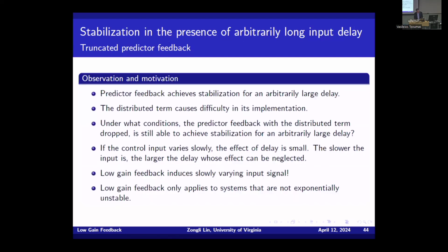So the motivation we had here is delay feedback. This is not good, right? Now, the idea here, you look at this point in two ways. One is, as I mentioned earlier, under low gain feedback, if the change of speed of u(t), the control input, is very slow, then you are more robust to delay, right? Extreme case, I have constant input, I don't care, you're delayed, right? So that's one way of thinking about that.